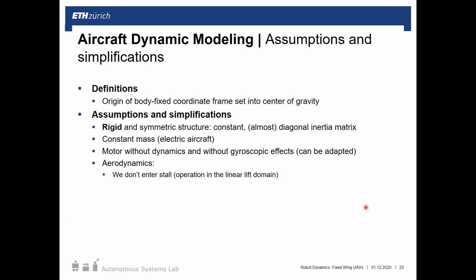So now down to aerodynamics. We talked about stall in the last video segment, and we're not going to model this. So you still need to know what stall is, where it will happen, and what kind of the characteristics beyond stall are. But for our model itself, generally planes are trying not to stall. So we're going to only model the part where we're still in that linear nice portion of the lift curve and not in stall. Lift and drag also, of course, exists on the fuselage. We're going to lump this with the rest of the aircraft lift and drag.